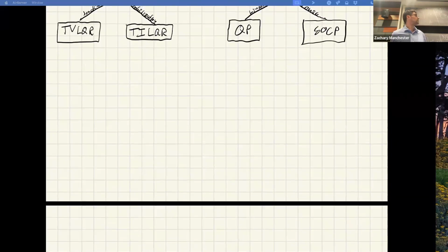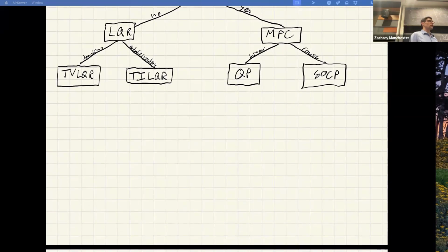Yeah. TVLQR is where ILQR comes in. TVLQR is not necessarily. It's like, let's say I've done nonlinear trajectory optimization, could be ILQR, could be DIRCOL, and I get some insane maneuver, let's say a backflip, or a drone doing some barrel roll, right? So that's highly nonlinear. You probably can't use a single linear system to model that entire thing, but you can linearize about every single point on that trajectory and get an A and B that are time varying along the trajectory. Then you do a Riccati and you'll get time varying K matrices.